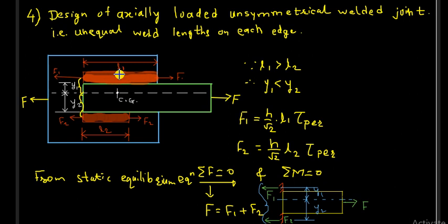Here in this case length L1 has the higher amount of weld bead material, so the center of gravity and the centroidal axis is shifted towards L1. So we have to take care of this, otherwise all the design procedure is similar to that of simple parallel fillet weld joint or simple transverse fillet weld joint, right?